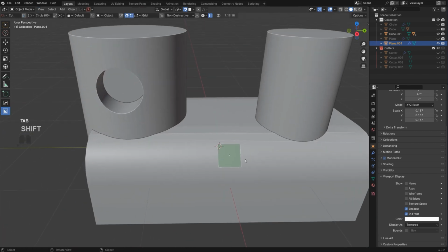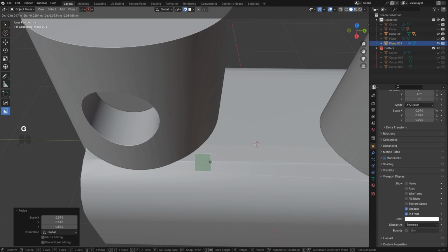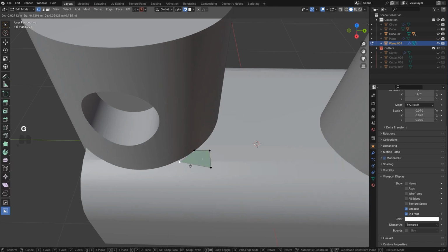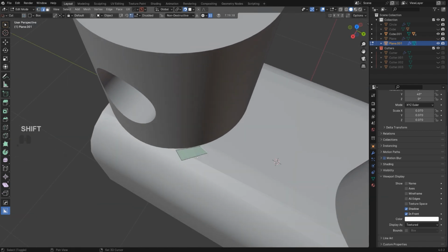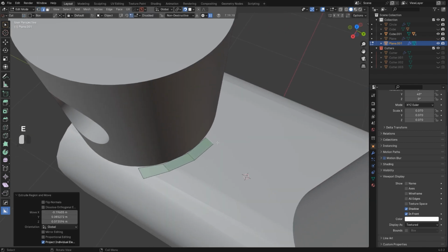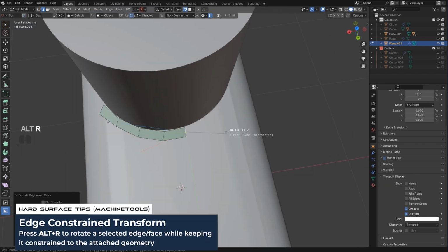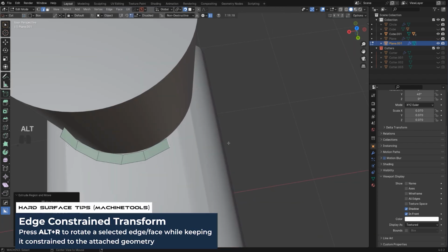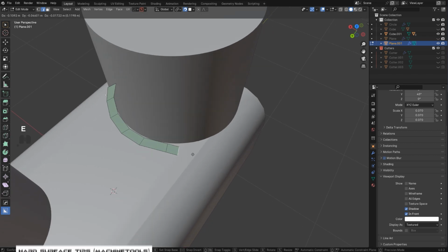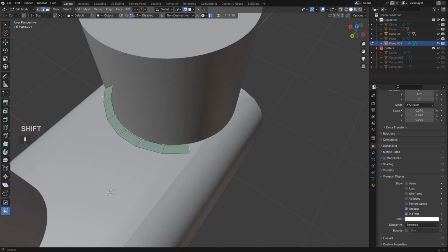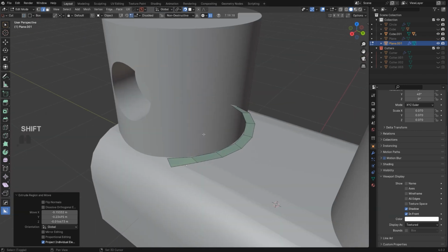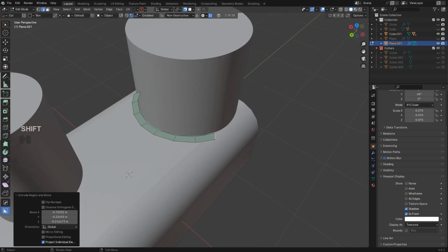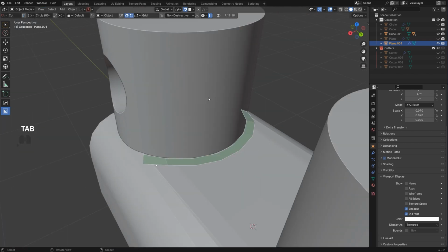So now what you want to do is retopologize this mesh around. So let me show you, just go around here and start creating mesh on top of this existing mesh. And the great advantage of doing it this way is that you can actually create your preferred topology flow from scratch. So for example, I can have this topology flow around this cylinder here, and I can actually choose the density of topology, so I don't have to go with this crazy vert count here.